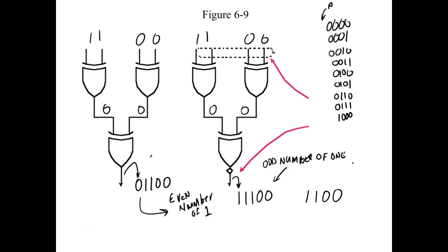Now, what we have to do is when we send this, I would bring in my 4 bits on one side, and my parity circuit would generate 5 bits, with 1 bit being what? Parity bit. This would go over to my receiver. Before my receiver accepts the data, you understand, it would have to be checked. So if I'm using my circuit that generates even parity, then this guy's going to have a circuit that detects what? Even parity.